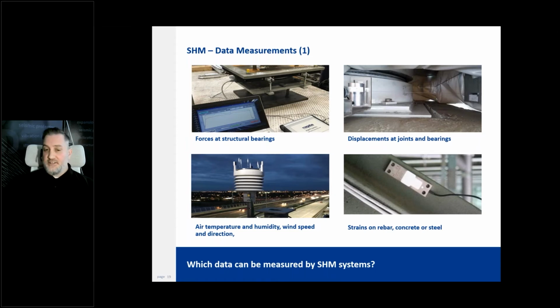The strain gauges, finally lower right. Stress and strain relationships are well understood for most materials, or for, let's say, many materials. This is a direct window into the behavior of the material. And this is a great example of how we can compare calculations to real world data, with something like the strain on a steel piece of rebar.